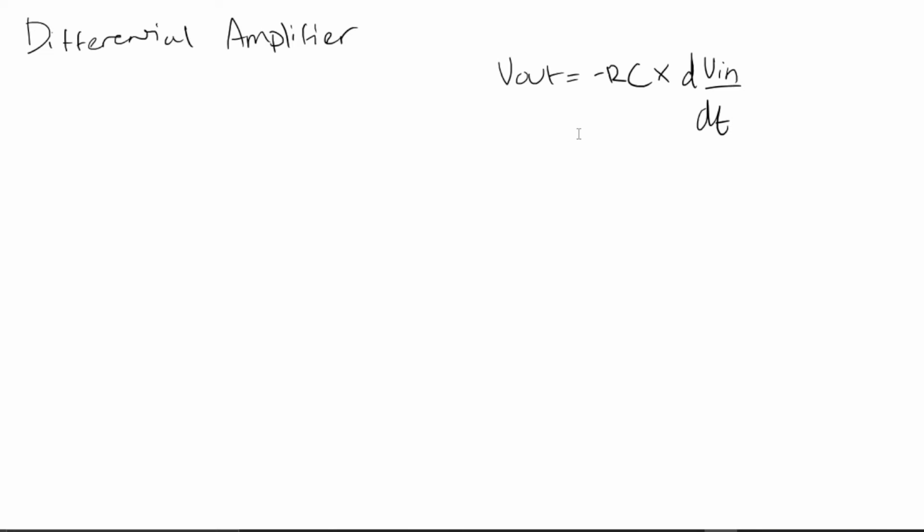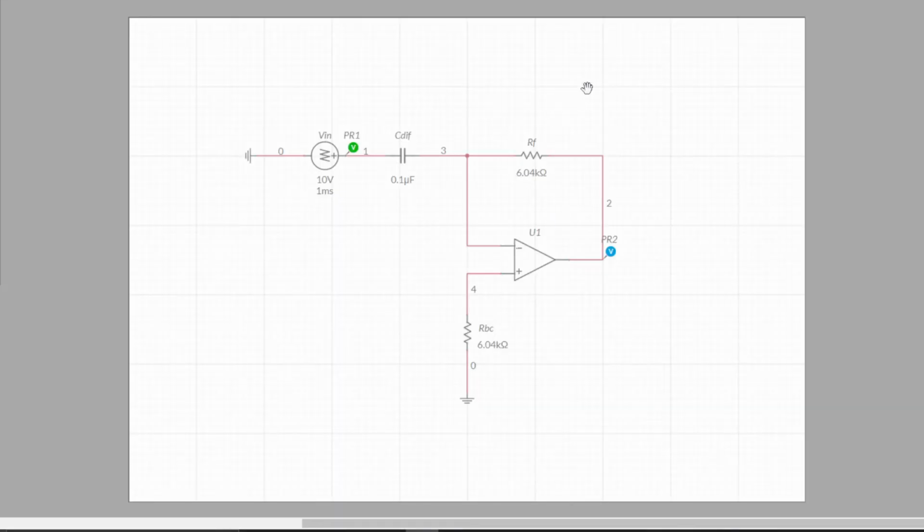And yes, I will just show you this in Multisim. So here we have our differentiator circuit with our capacitor and resistor. The compensation resistor can be placed at the inverting terminal, along with the compensation capacitor in parallel to the feedback resistor. These two components help to alleviate both stability and noise problems, which are then allowed to be corrected. So enough of that. We'll run this.